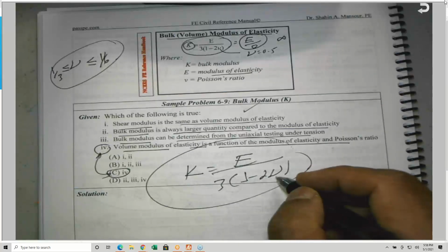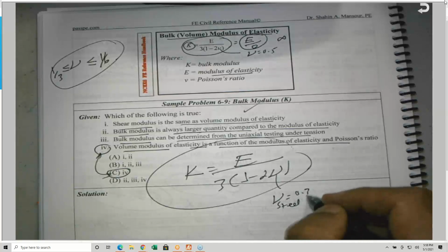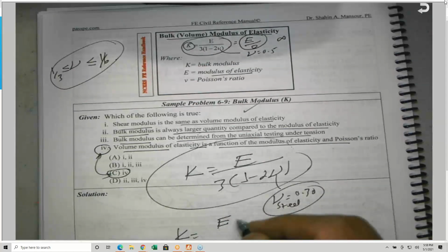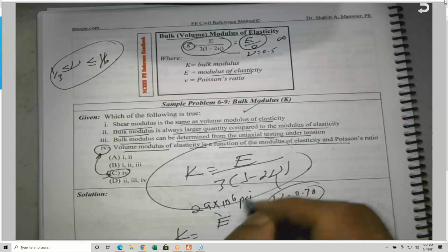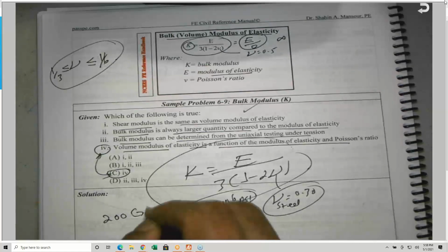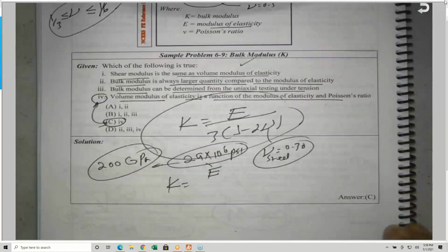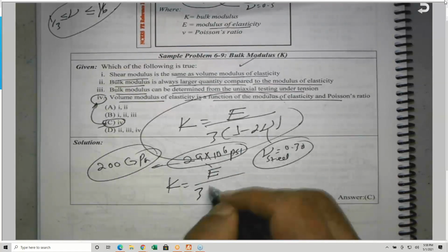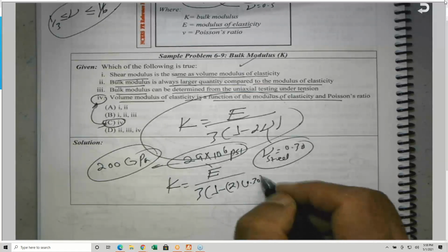So if you take, for example, Poisson's ratio for steel, which, as all of you know, is 0.3, the one listed in the book. So K is equal to what? E for steel, which is 29 million psi. Do you remember this number? As I always joke with you guys, or 200 gigapascals, GPa. Any civil engineer, even while dying, should remember these two numbers. So, divided by 3 times (1 minus 2 times 0.3), and I will use 0.3 for steel.